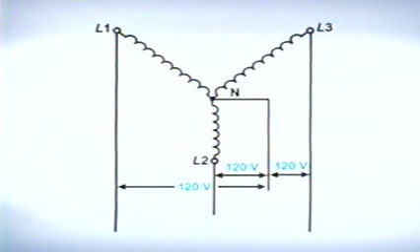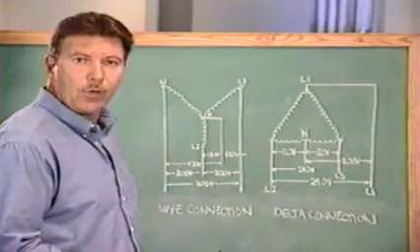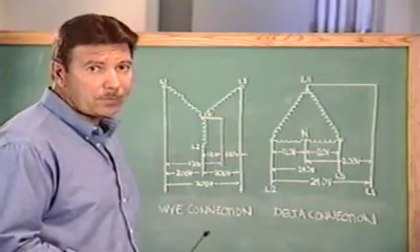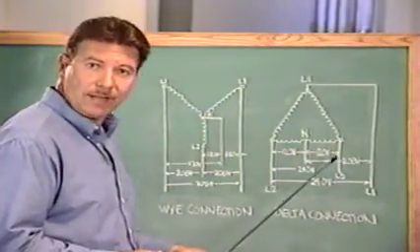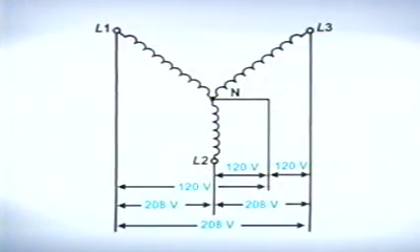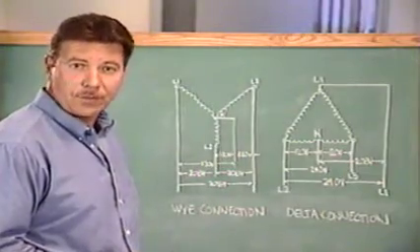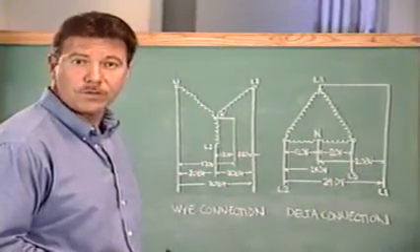Voltage measurements from L1, L2, or L3 to neutral will yield readings of 120 volts. Note that the Y connection has no high leg, which is the main operational difference between the Y connection and the delta connection just discussed. Voltage readings between any two hot legs will produce readings of 208 volts. The three hot legs to neutral can be used to power circuits requiring 120 volt service.